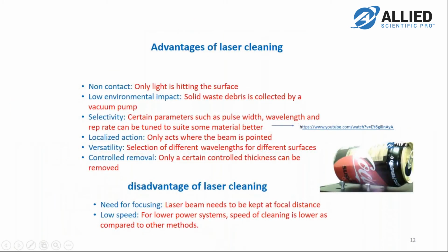So next, let's look at more advantages of laser cleaning. It's a non-contact process, only light hits the surface. There's low environmental impact. Solid waste debris is collected by a vacuum pump, and it's very selective, because certain parameters such as pulse width, wavelength, and rep rate can be tuned to be suitable for some material better.